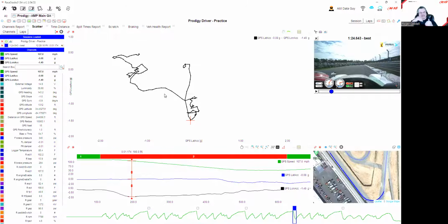But the next thing I would be doing is, is it the track that's making me do this? Is it the car? Or is this me as a driver? Should I be a little bit more conscious of starting my turn in when I'm still hard on the brakes, and start releasing the brake pressure as I'm turning into the wheel, and not losing this available grip that I did not use.